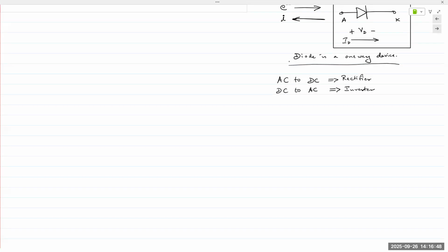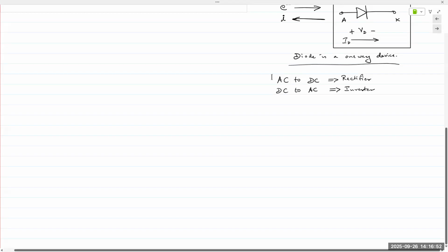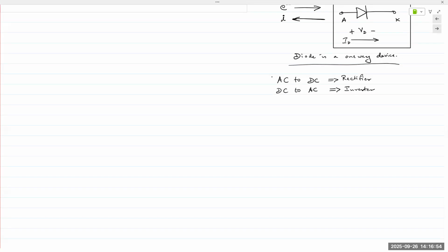Okay. So all rectifier circuits, all power supplies have a diode at the front end. A diode is a one-way device, and AC goes in both directions. If you feed that to a diode, diode only conducts in one direction. And so the preliminary output of a diode circuit is kind of like a half wave or the positive peaks of an AC signal.